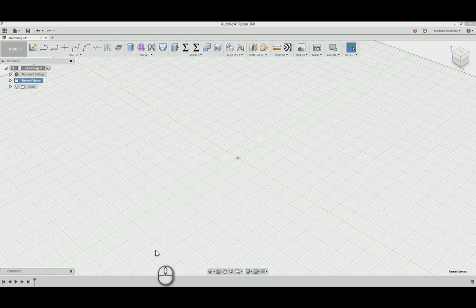Next thing, I want to talk about navigating. This is just mouse control. The main thing that you're going to use with navigating is this wheel. That's the magic navigator button. To zoom in and out, you push the wheel away. You can set things in preferences. Say you are used to SolidWorks or some other program.